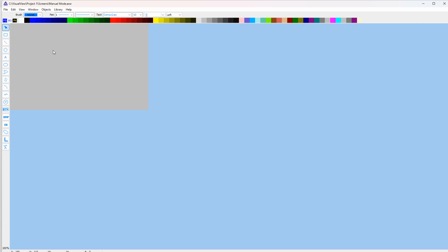The reason I do that is I'll run these screens fairly small so that when I run them and I'm watching the logic in the PLC, I can control things with my HMI screen in the front, but I can see the logic behind it, because I'm going to make a pretty small HMI window to use. Okay, so we've got this screen, and you'll notice over on the left what we call screen objects, or the objects we can use in our project.